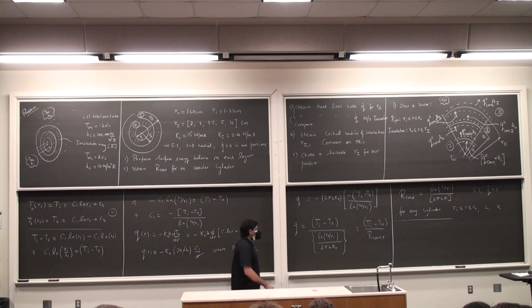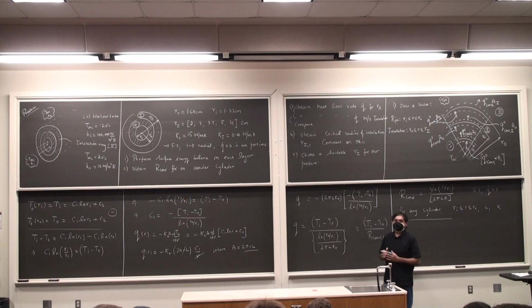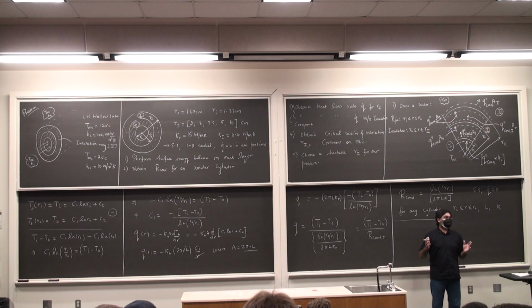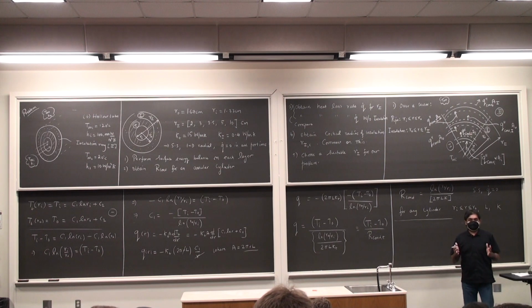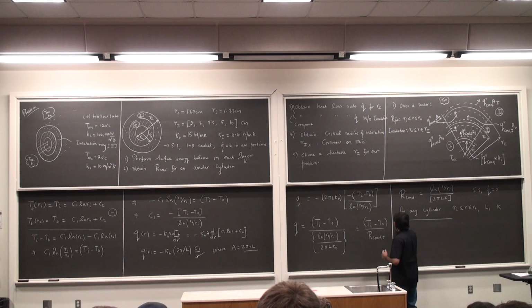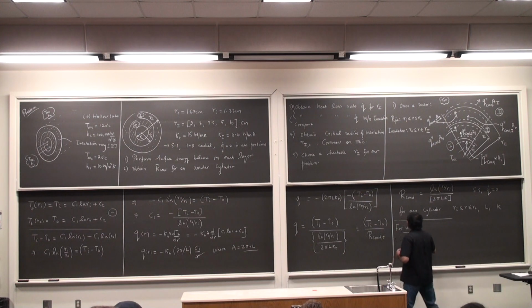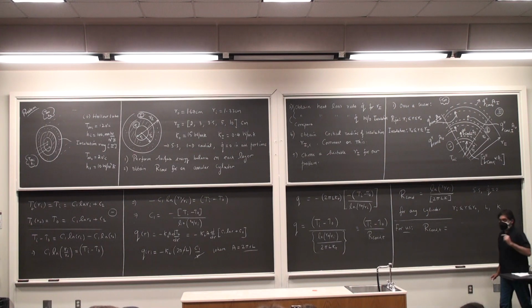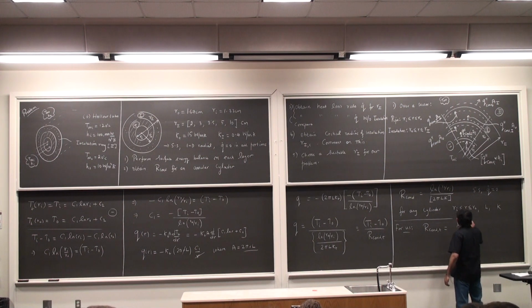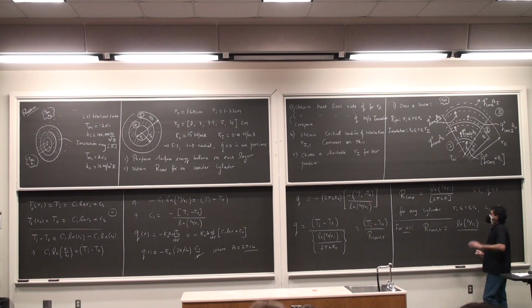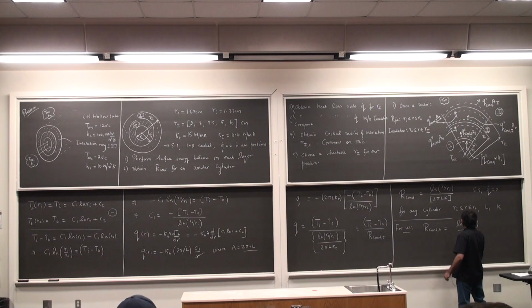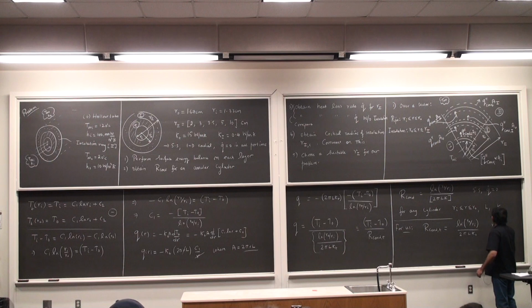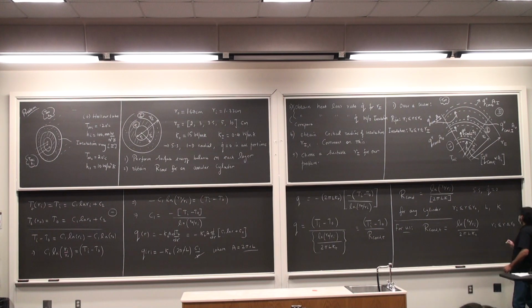We're going to make use of it though. So we go back to our problem, where we have drawn the resistive network. Now we have a placeholder for this conduction resistance, so I'm going to write it for each of these things. So for the pipe, the conduction resistance is logarithm R naught by Ri, the larger radius by the smaller radius, always remember it that way, divided by 2 pi L kT for that radius range.